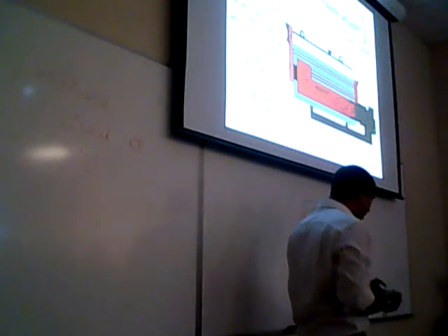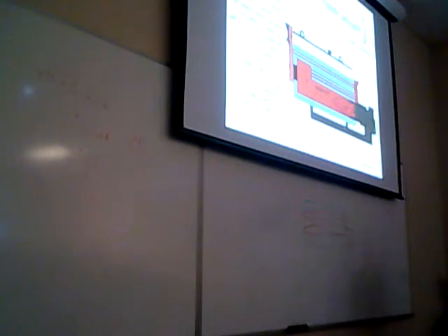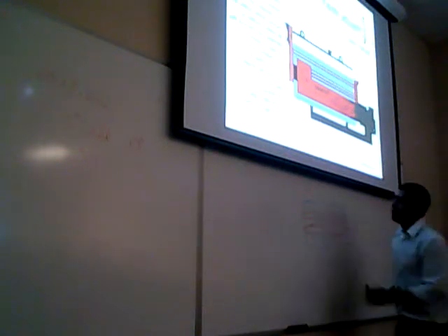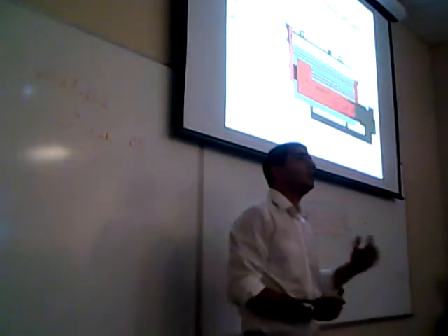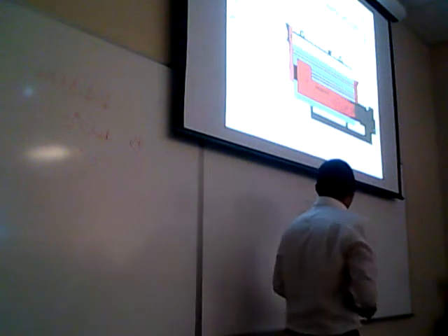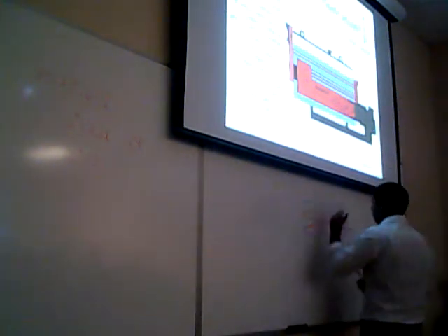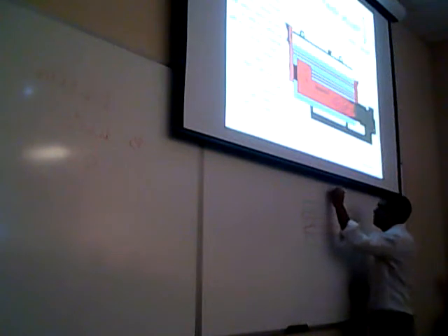Why is it so important to know how many passes the boiler has? It's important because if you want a high rate of transfer, you're going to need more passes, depending on the design and the temperature, because you have steam here.